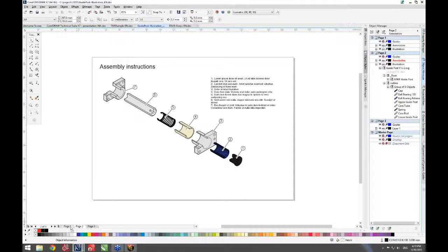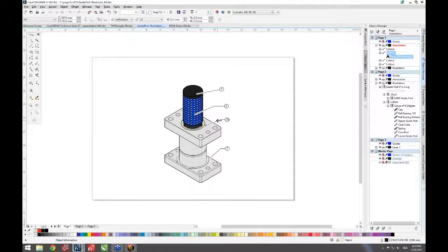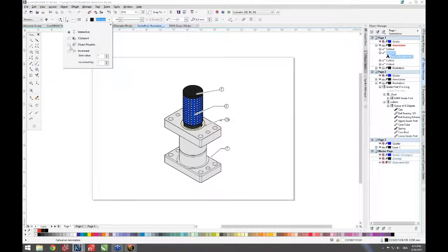And what you see here as well, also on page 1, I have added callouts. So this uses one of the unique Corel Designer features to add numbered callouts or text callouts with halos, so the white mask around those lines that makes it very clearly readable as an illustration. That's all done in Corel Designer, very simple with the callout tool, for example. So you can use automatic increment. That's what we've used here to do this numbered callouts and things like that.